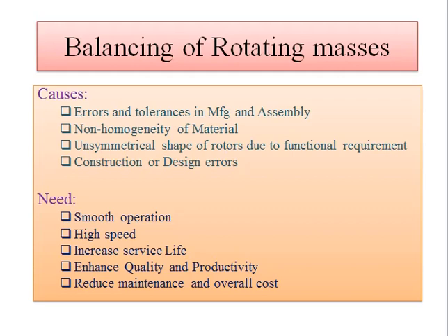Then what is the need of balancing? Balancing is needed for smooth operation of machines or components. Generally, most machines work at high speed, and at high speed unbalance will create vibration and noise. We know that unbalance is basically due to centrifugal force. Whatever the unbalanced mass, it will rotate about the axis of the center of rotation, and that mass will create a centrifugal force, and that centrifugal force needs to be balanced. Otherwise the magnitude of the centrifugal force is huge at high speed, and it will bend the shaft, or it will create vibration and noise in the component. So the need of balancing at high speed is very important.